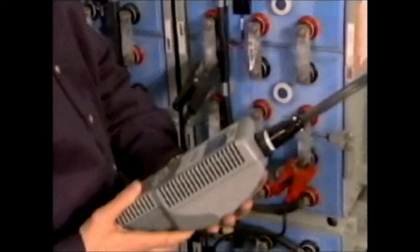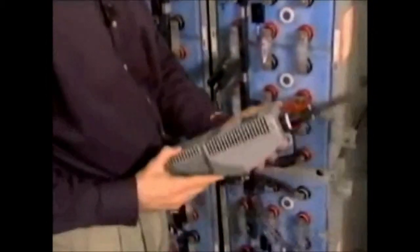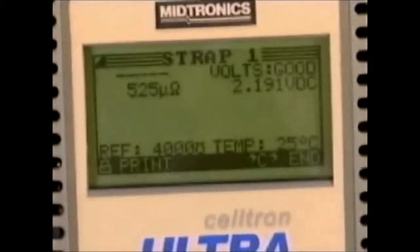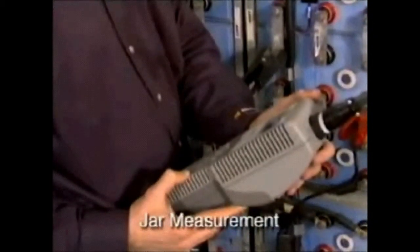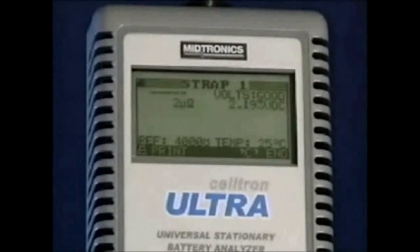After we have tested both jars and straps, we can review that information. For example, strap 1 reads 525 microohms. We expect to see a slightly higher measurement of the jar compared to the strap measurement. We expect the conductance measured to drop when we measure the strap. You can scroll through all your collected information to locate a pattern. The resistance or voltage drop in each of these battery measurements and strap measurements should be fairly even. Anything unusual indicates a potential problem with the strap.